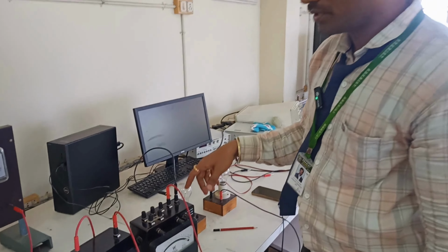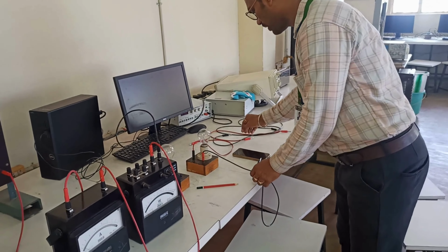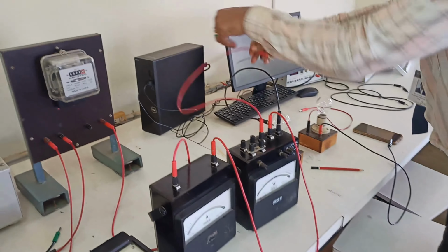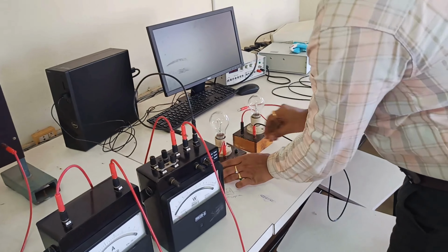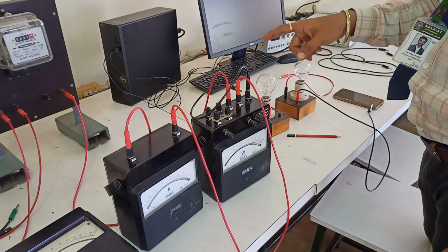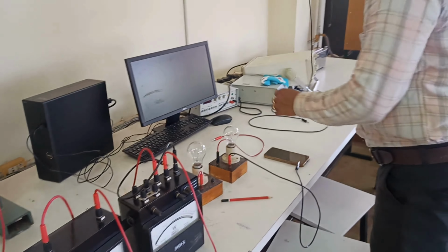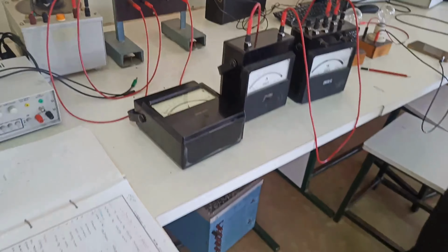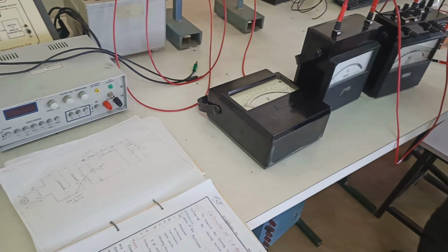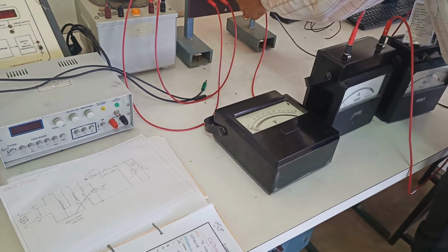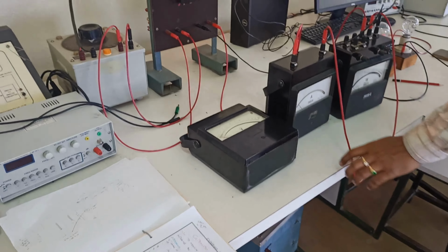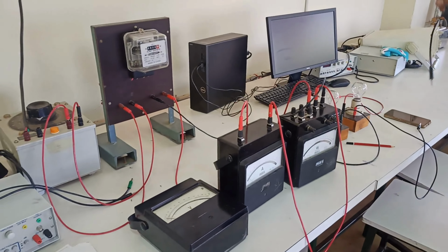Okay. And now from L it has to go to the load. So this is the terminal L. So from the load we have to connect to one end of the lamp. Okay. And now you can see here the red color wires are used to show the flow of current. And the return path I am going to show with a black color wire. So from the lamp, as in the circuit diagram, it goes to the neutral. And one more connection from the wattmeter also goes to the neutral. So that wattmeter connection I am also indicating with a black color wire.